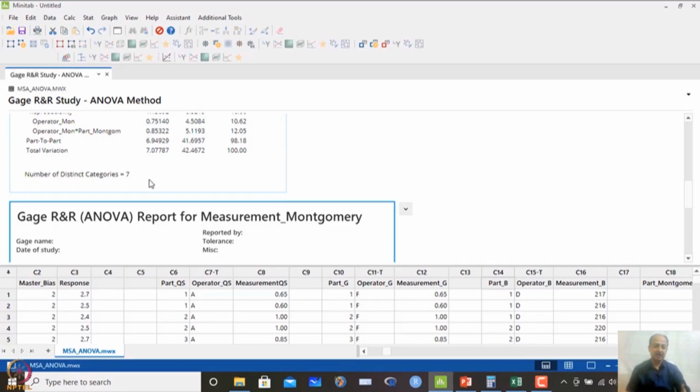So, it is expected that when we select the range of the parts within the operating range of the CTQs, we get the values throughout the tolerance. So, we expect that at least the instrument should be able to distinguish at least 5 different categories, because parts are in different categories.